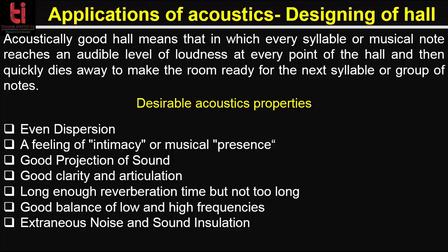A good balance of low and high frequencies is required. A proper balance of high and low frequencies of sound is usually a matter of boosting the bass. If the auditorium has a short enough reverberation time that approaches the inverse square law, then the bass loss problem is encountered.